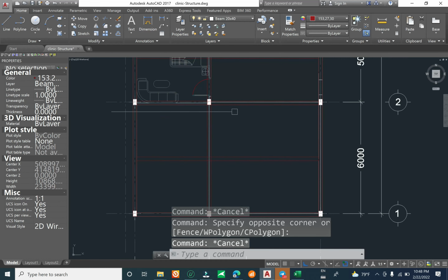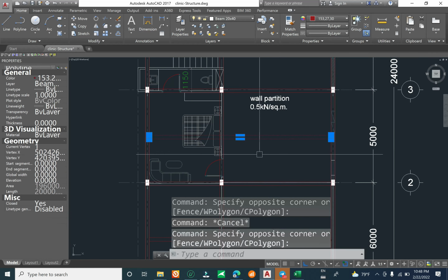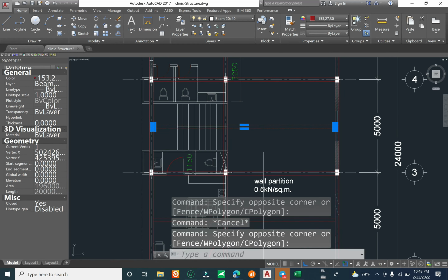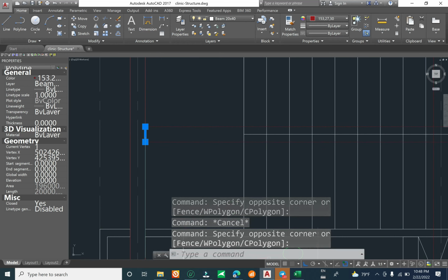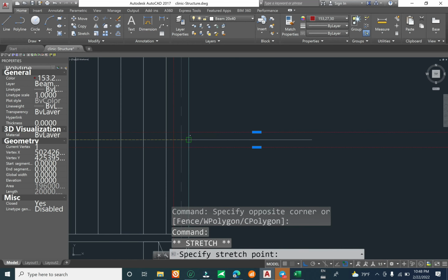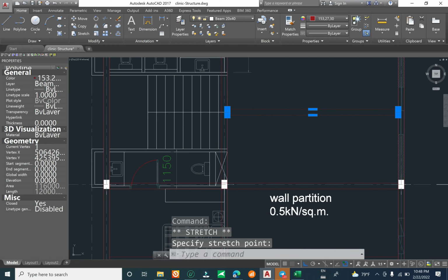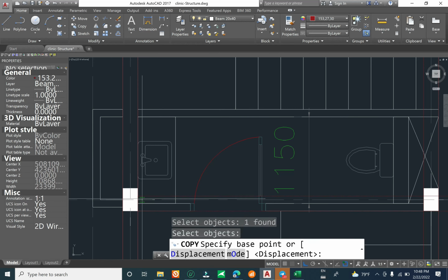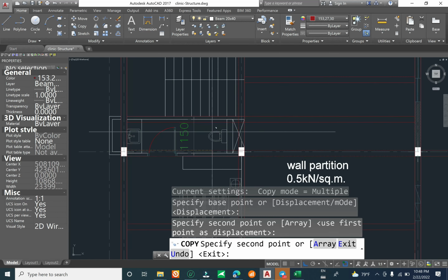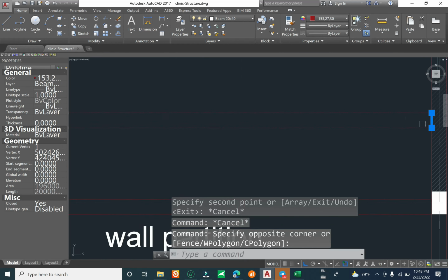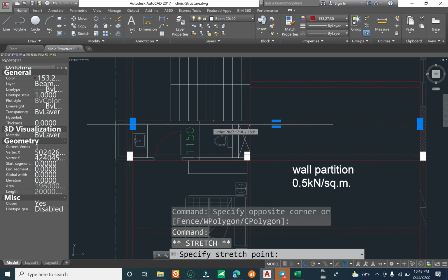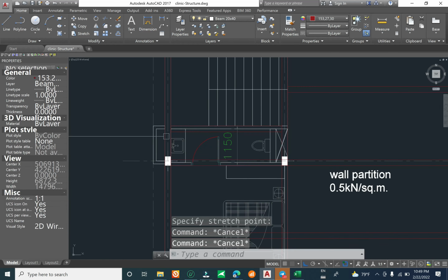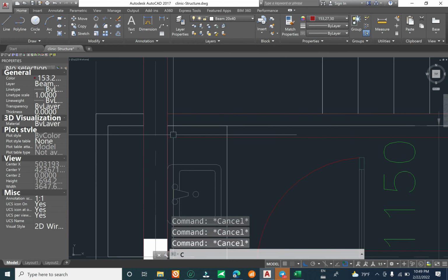Okay, now you see here, and this one we add another beam. Okay, the same, and this one we add another beam, but you have to make sure this beam does not clash with the stair. Okay, now we have to move it, and in the location we have to add another beam. Okay, this one we add another beam to support the opening of the stair, and to support this wall you can add a small section for the beam.